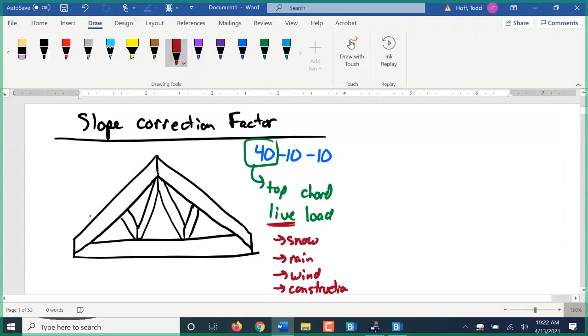Technically, if you look at specifications, they tell you should stack your extra shingles right down on the gable. And the main reason for that is because it's just right above your support wall, so the truss isn't really holding it. It's the support wall underneath it that's holding it up. But anyway,